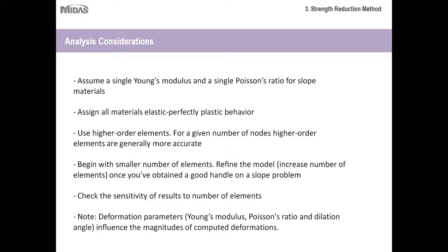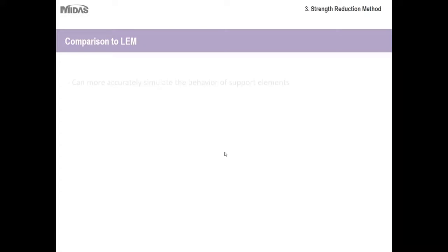So more often than not, when a model has an erroneously high or low magnitude of deformation, it usually means that one of these values is off by an order of magnitude, or it's been mismatched. So that's another important thing to remember when you're entering your parameters.